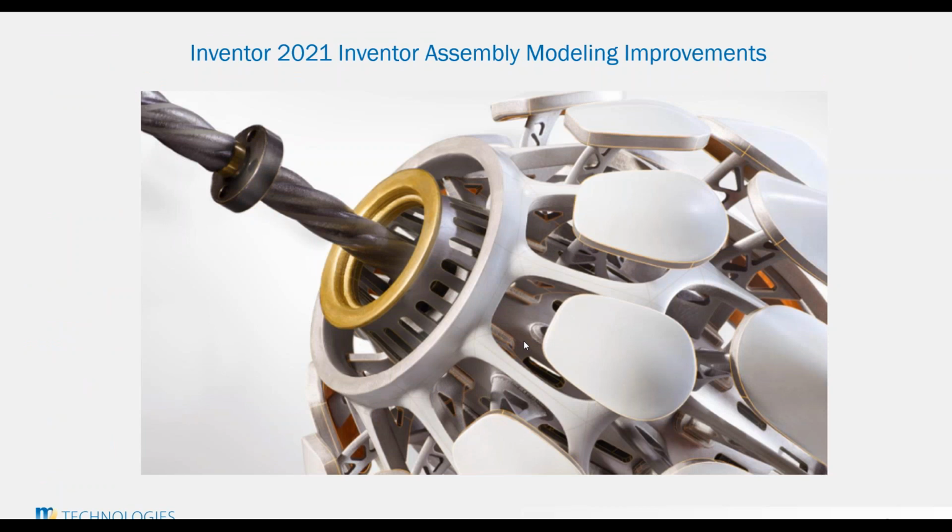All right, and hopefully that was a little bit more informative. There was a segment there that, due to time constraints, I did not talk about, the extended flange, but for those of you who are working in the sheet metal environment, that is a nice feature. It allows you to, as you saw on the video, highlight a reference plane to extend to. Again, it's a new feature that came out of the ideas forum, very useful for the sheet metal environment.